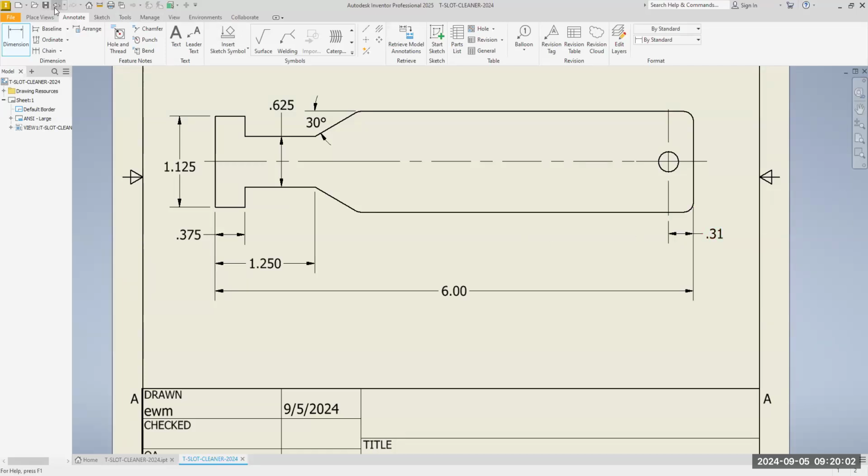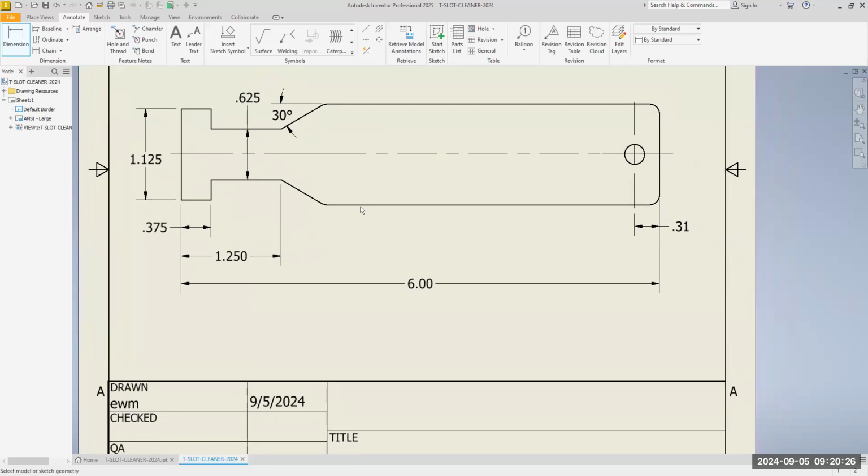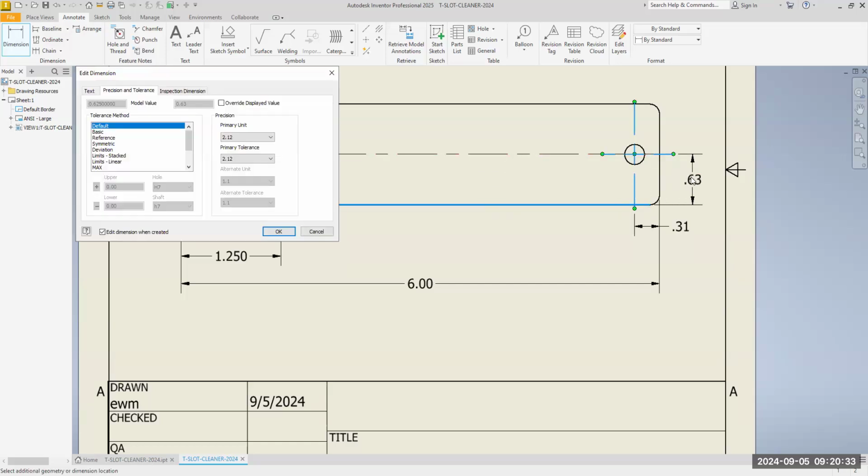I'll show you one more time what I did. I went to dimension, clicked on the center, drag. Now watch, I come over here and I kind of kiss that dimension here for a second, right? And then you move that little yellow dot back over this way, and then click and say okay, those dimensions are lined up now. We need to put this dimension here from here to here. And say okay.